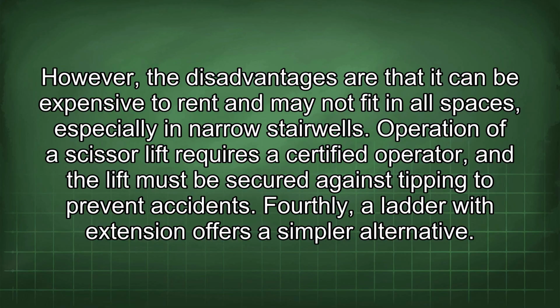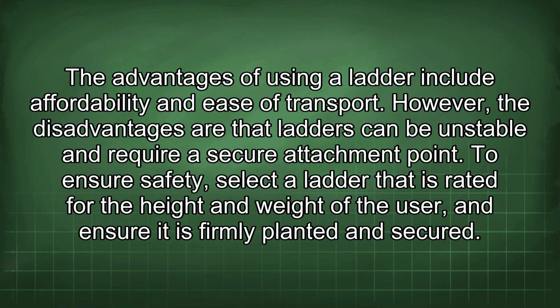Fourthly, a ladder with extension offers a simpler alternative. The advantages of using a ladder include affordability and ease of transport. However, the disadvantages are that ladders can be unstable and require a secure attachment point. To ensure safety, select a ladder that is rated for the height and weight of the user, and ensure it is firmly planted and secured.